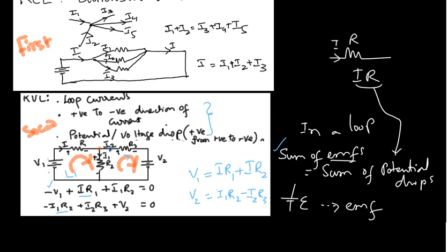This is R2. Okay. So in this case I1 R2, this is in the positive direction, but then you are going here also I2 R3. So minus I1 R1 I said, right? Why did I say minus I1 R1? Because this direction goes like this, whereas I1 goes in the other direction. They are opposite. Always you should take the clockwise. So that's why this has become minus and this has become plus.